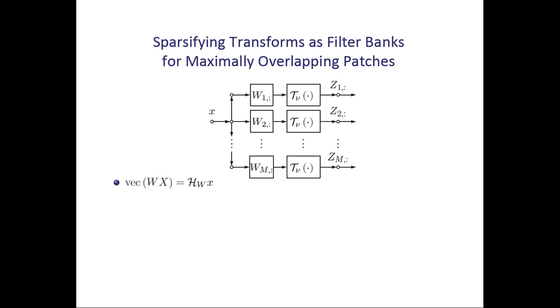It's an equivalent interpretation. And once we talk about filter banks, there is the concept of perfect reconstruction. If you've looked at filter bank theory, what you wanted to do with a filter bank was to guarantee that after you filtered in the bank, you decomposed the data into these outputs from these channels, it was possible to recover the data back. So there is a condition. For example, if all these filters are 0, of course, you're not going to recover. If all these filters are the same, you'll get a blurred version of the input.